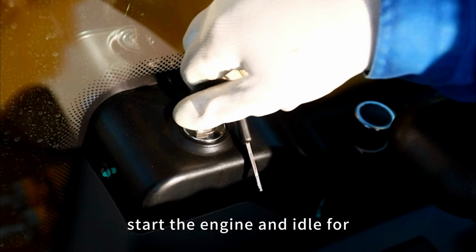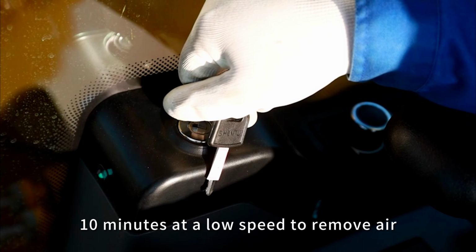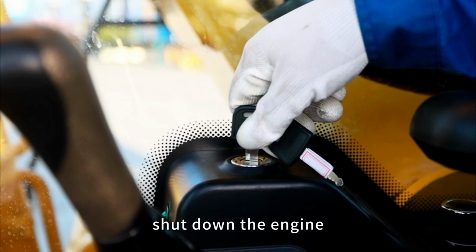Install the oil filler cap and tighten the bolt. Start the engine and idle for 10 minutes at a low speed to remove air. Shut down the engine.